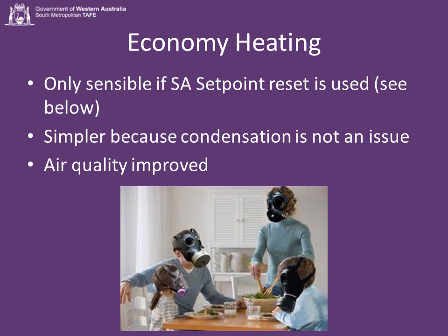It's much simpler doing the calculation because it's based purely on temperature. The biggest advantage of using more outside air is that it improves air quality. Numerous studies have found that using too much recycled air leads to several problems. Firstly, an increase in humidity in the air-conditioned space. Increased humidity tends to lead to damp walls, and that leads to mold.